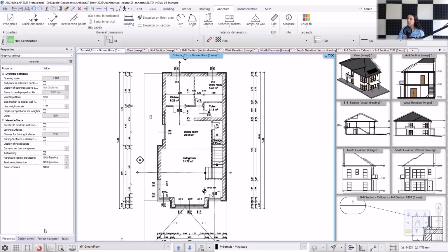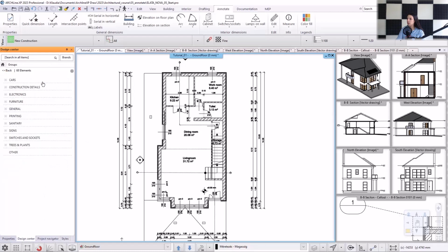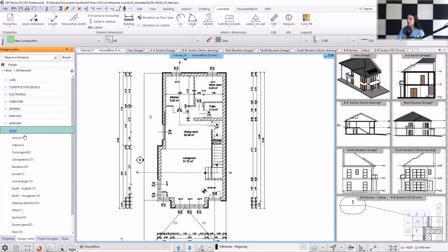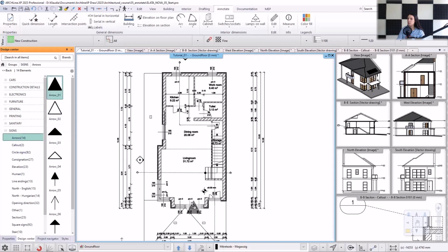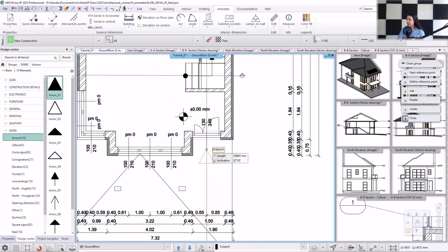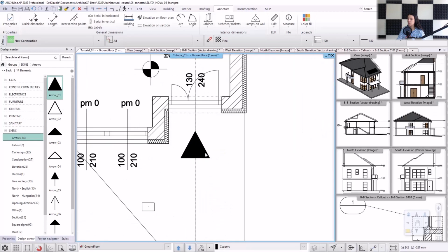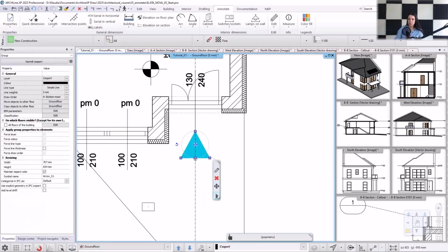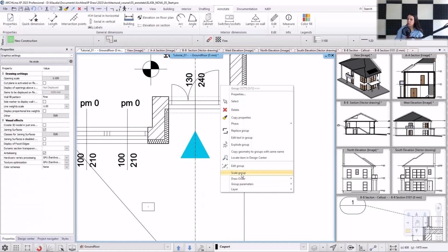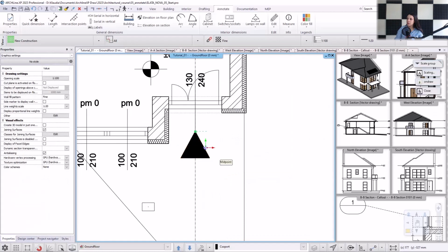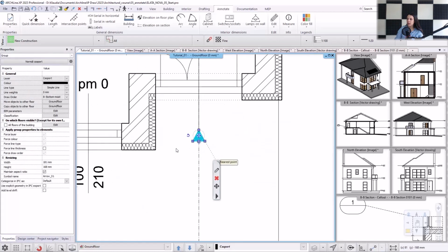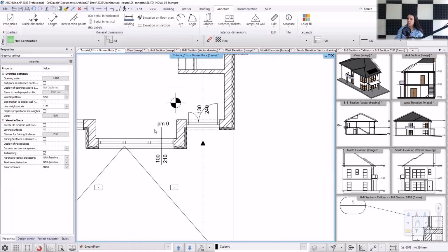In the Design Center, in the Building section, the last option is Groups. You can find more 2D symbols here, under the Signs menu. I'll place an arrow at the entrance. I'll use arrow 01. There are 2 ways to modify its size. I'll click on the icon and use the local menu to scale it larger or smaller. Alternatively, you can adjust the width and height values in the properties.